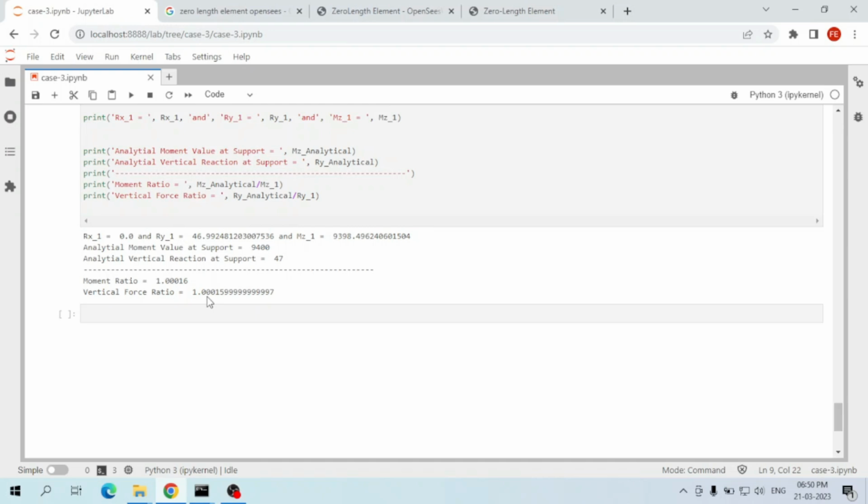We have to perform it against a known result. The known result can be experimental data or an analytical solution. In project 1, we performed a kind of validation using the experimental data, and in this project, we are performing the validation against a known solution, that is the analytical solution. After validating your finite element model against a known solution, you are good to perform parametric studies on similar geometry.